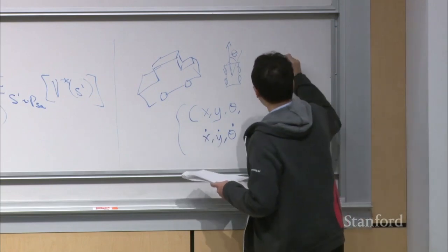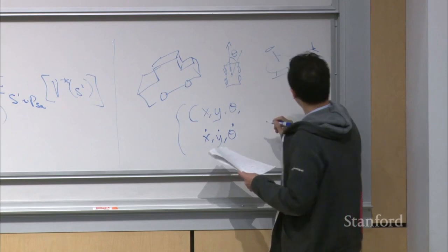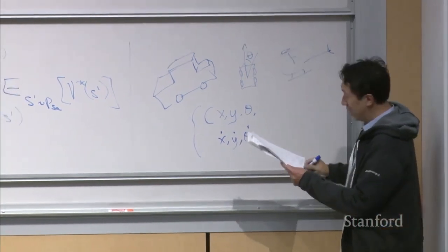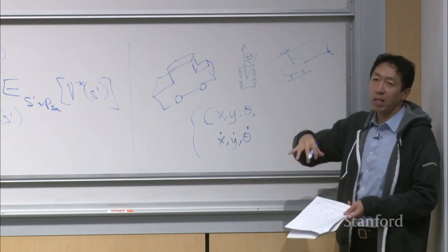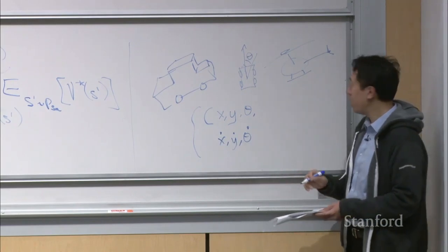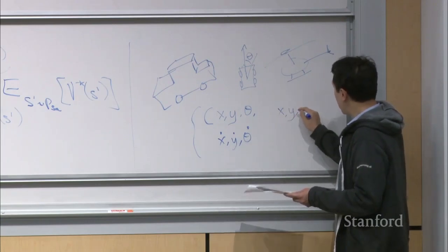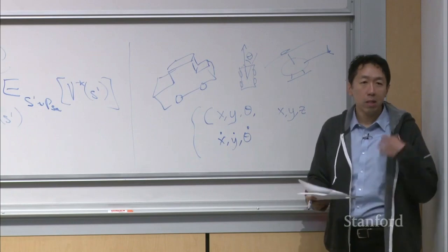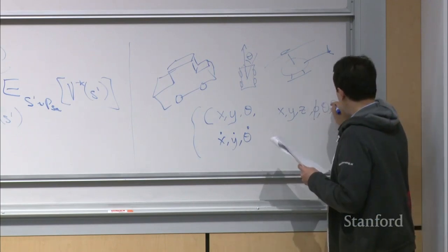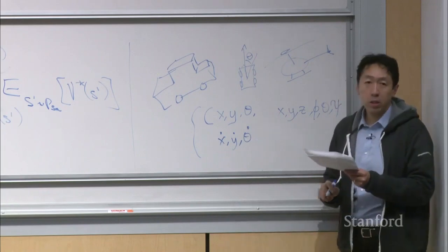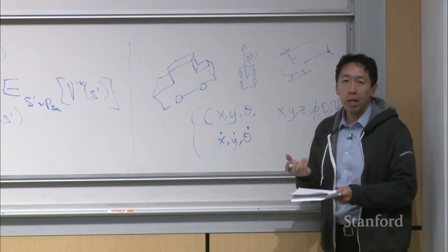All right, how about a helicopter? How do you model the state space of a helicopter? A helicopter flies around in 3D rather than driving around in 2D. A common way to model the state space of a helicopter would be to model it as having a position x, y, z, and then also a 3D orientation, which is usually modeled with three numbers that we sometimes call the roll, pitch, and yaw.